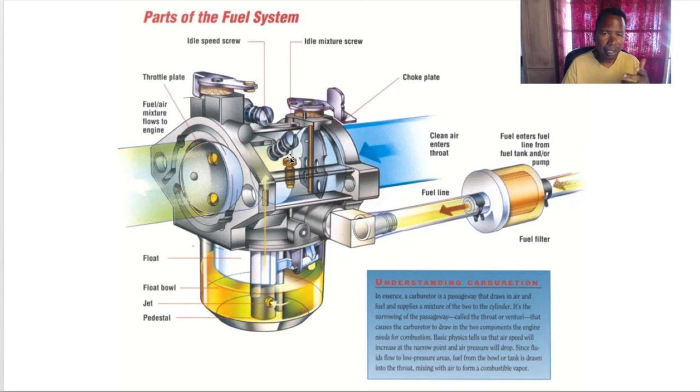If that didn't help, we either had to find a vacuum leak or go internally inside the carburetor and clean a port out, to see if it had bad flow, a bad gasket, or a plugged air bleed. At the basis of the air fuel mixture is a rich condition or a lean condition. Again, if it's running rich and I make a vacuum leak, the car will smooth out, so I needed to figure out why it's running rich. For example, I would have to turn the screw in to lean it out. And rich means too much fuel. If it was running lean and I put my hand over the choke or added propane and it smoothed out, I had to find a vacuum leak or turn the screw out counterclockwise to richen up the air fuel mixture.